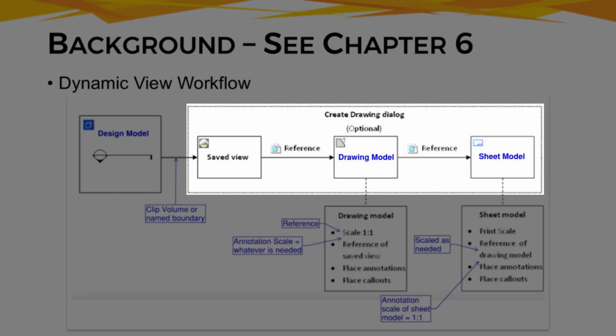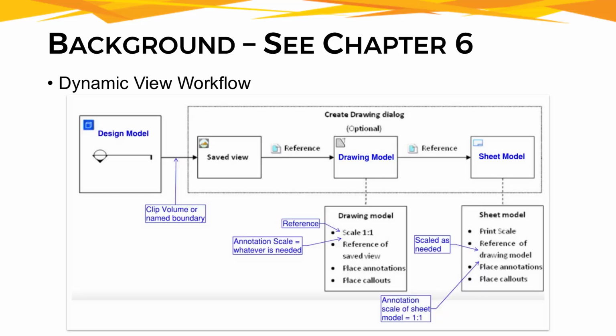If using these tools, all the way from the saved view to the sheet model, which is shown within the Create Drawing dialog portion, will be done automatically for you. Although, again, in theory, you could do all the steps separately. It's important to understand the steps that the Create Drawing dialog is doing for you in case there are any issues and you need to either start over or make adjustments.